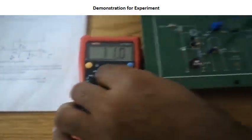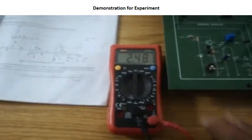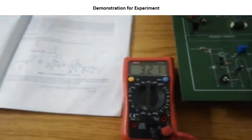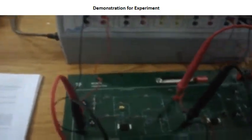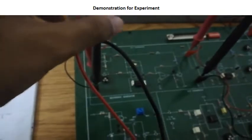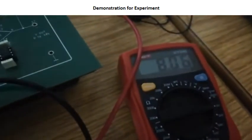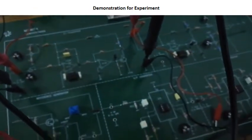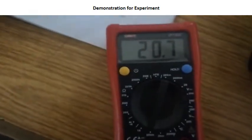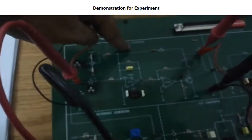It needs to be adjusted at micro or milliampere mode. According to the circuit, it should give the 20 milliampere current across the 8 volts. So we will see after adjusting some parameters. Here is 20.7 milliamperes, which is very close to 20 milliamperes. It shows our design is right.